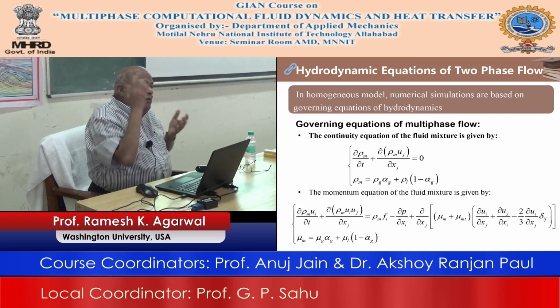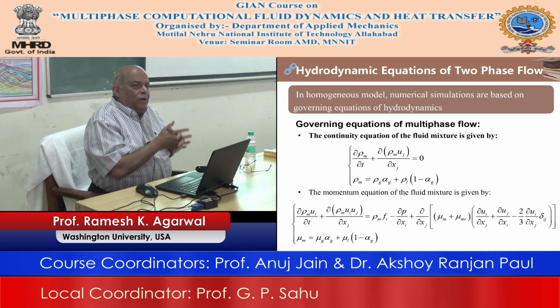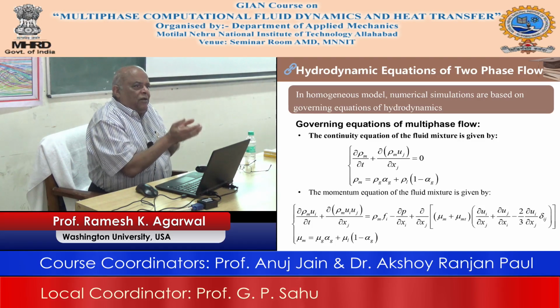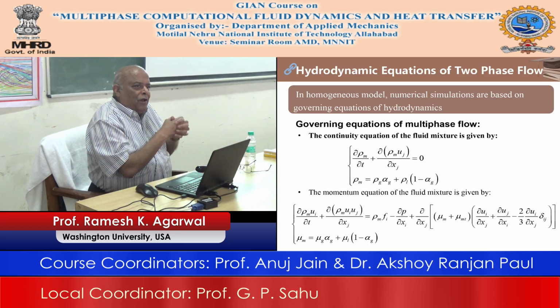Okay. So, initially you are right. Alpha L in the entire grid is going to be 1, and alpha G is 0. But in the iterative process it will keep on changing, because air is going to be forming in some places. It will no longer be true that alpha L is equal to 1 and alpha G is equal to 0, because there will be places where there is alpha G and next door it will be alpha L.